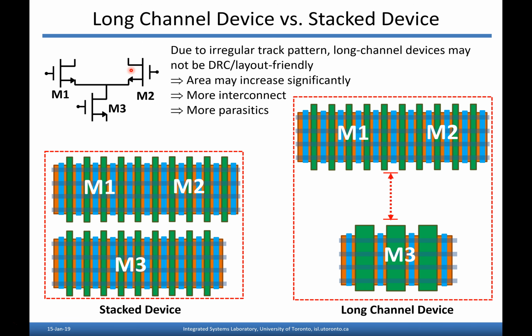And when you're in the minimum gate length world with FinFETs, you've got to be on this very fixed pitch, right? Everything's got to be this set pitch, not just for the gates, but for the low-layer metals. If you're going to switch from that to a longer gate length, there's all kinds of minimum spaces you have to allow in order to break that fixed pitch.